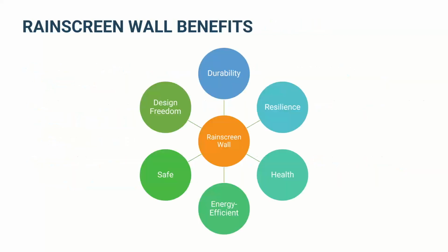So this is why RAiNA was formed, to promote the use of Rainscreen Walls, and there's really a ton of benefits. I would say number one really is just at the top there, the durability aspect. You want your buildings to last a long time. Managing water appropriately is the best way to do that. Resiliency, by that I just mean remaining functional in the face of environmental changes. So we're seeing stronger storms, more severe weather events. Just having buildings that are adaptable, that can handle those things is really important.